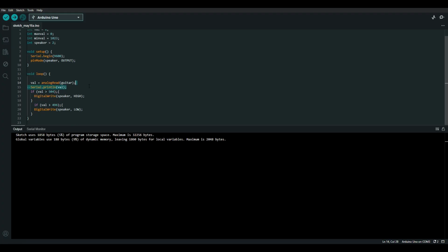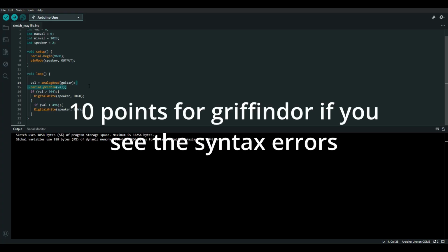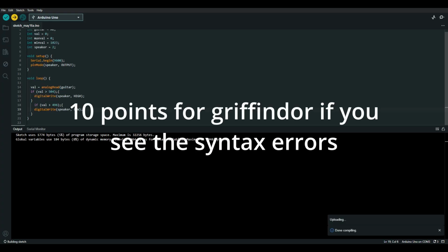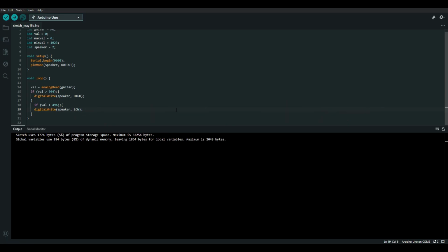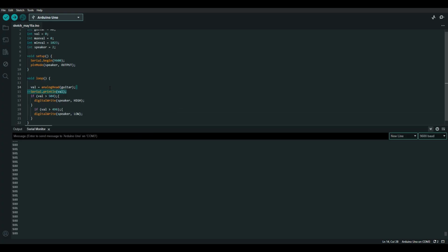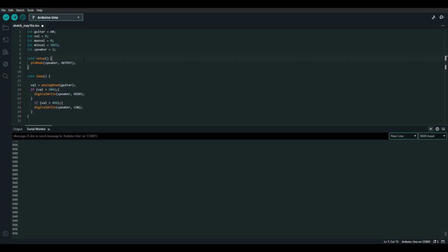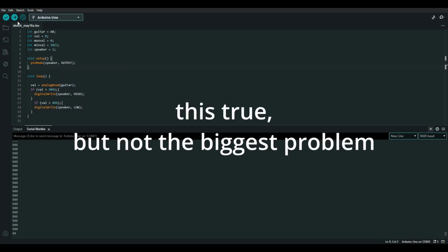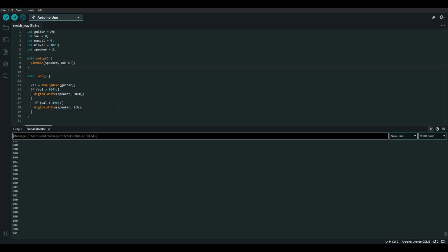I'm just going to run it and let you hear it through my laptop microphone. It's gonna sound horrible, but it's not gonna sound pretty in real life either. So, okay, let's hear it. It seems to just make a horrible noise. How interesting. What I'm thinking is that maybe the fact that we have our serial running ruins the clock rate of the Arduino. Okay, next possibility.